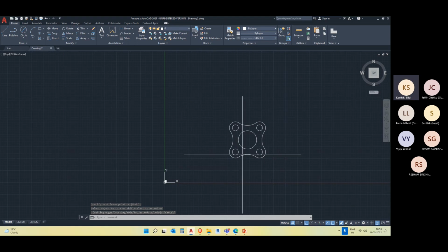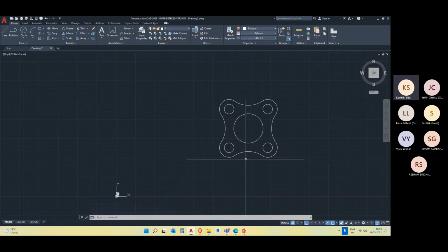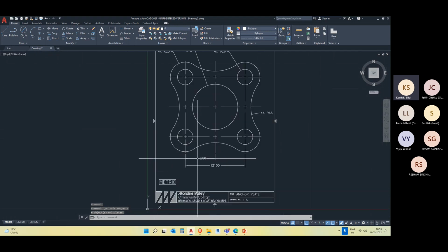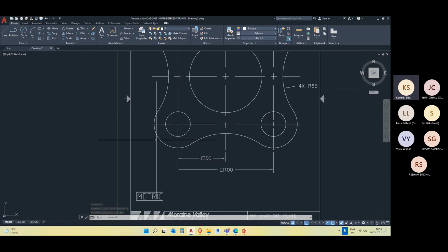It was very difficult for me to change, to erase the unwanted lines, unwanted circles. Now it was easy. After your job is done, you can just hit that object isolation. Now end object isolation. Now we have your lines back. After that, you have to see until where the line is traveling.